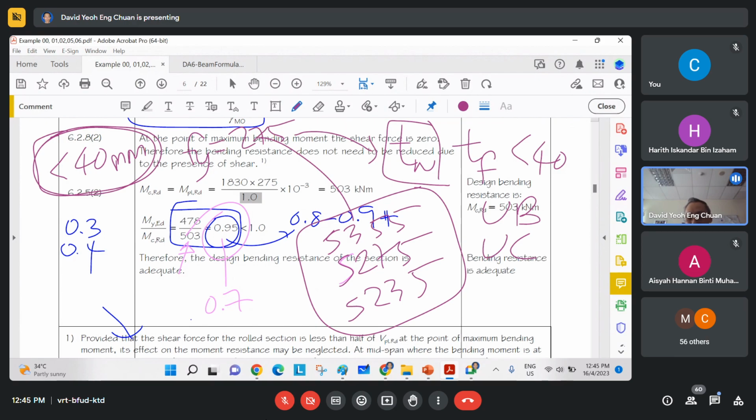But in actual practice, for reinforced concrete sometimes the architect can give you the size. But when you have a drawing and it comes to steel, the architect cannot design, they will write 'to engineer specification'. So that's where engineers have to do the design. You decide whether you want to use a section of UB or a section of UC. But when it comes to a beam, we always want to have it in a rectangular edgewise.